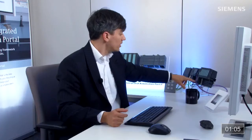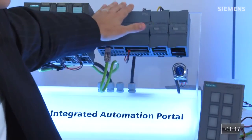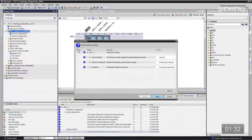So ultimately, if you look at the automation architecture over here, we can generate diagnostics for the channel layer. So let's say, for instance, a wire break to a module failure. We could even have an entire rack failure or another physical layer diagnostic, including HMI and even the master. Any kind of diagnostic can be automatically generated, and you don't have to write one line of code to achieve this. Also, at the exact same time, all the partner port connections on Profinet are also going to be compiled as well. Now that we're finished, we can click the load button.